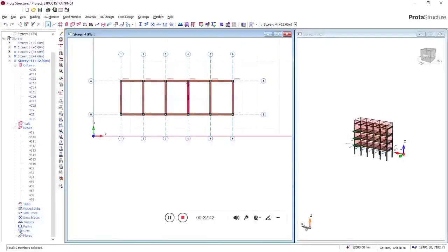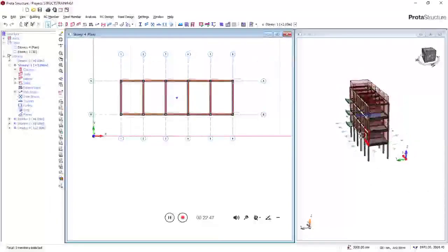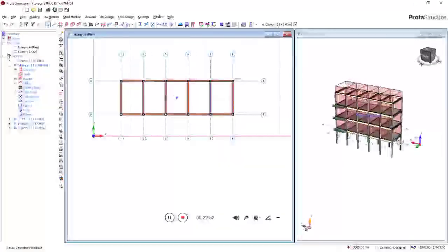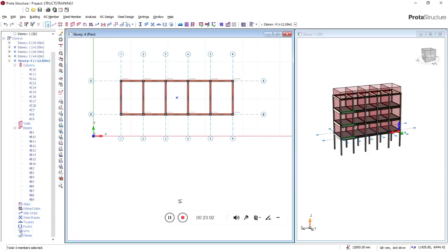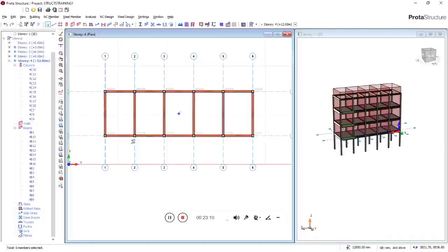So what we should do again is this. Now we are good to go to run our analysis. We have inputted the loads: the live load, the dead load, the additional dead load, the cantilever load. We have drawn a slab strip. We have inputted the load, we have done our slab strip and every other necessary thing. So the next thing to do is to run our analysis. But before you run the analysis, I want to show you one or two settings that will guide you in producing a nice result. So you come to settings.